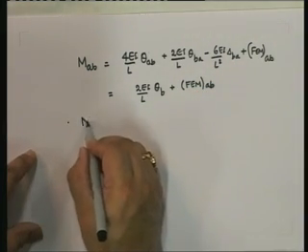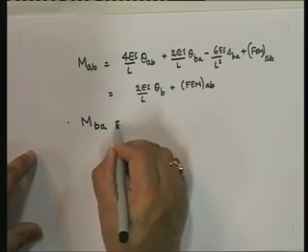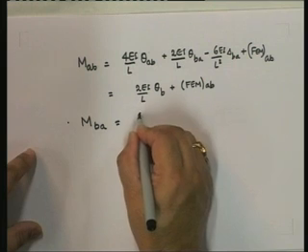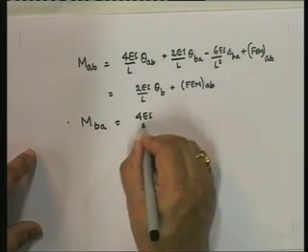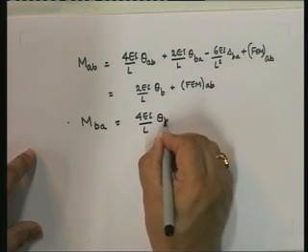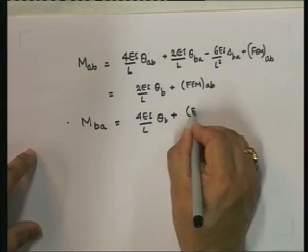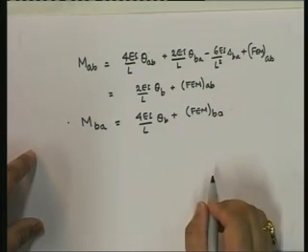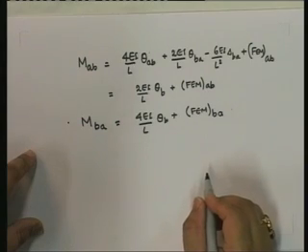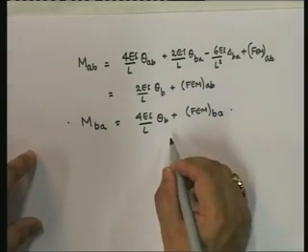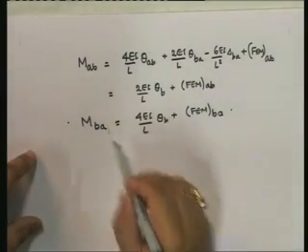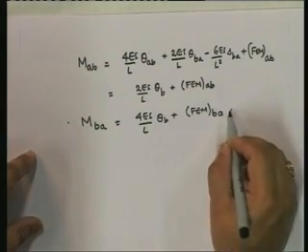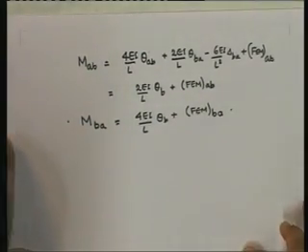Similarly, I can get, and I'm not going to write down this equation, I can write down the same equation, but if we put it in, we will get 4 EI upon L theta B plus fixed end moment at BA. Okay. So now, so you see MAB and MBA are in terms of theta B. Okay. Now these fixed end moments I'll find out a little bit later.